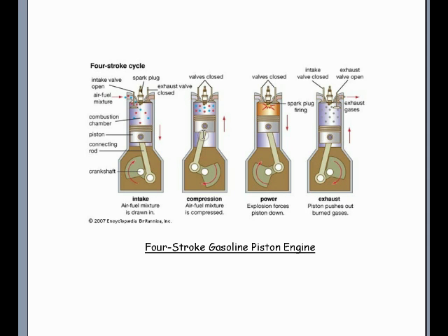Next comes the compression stroke, for which the air-fuel charge is compressed to before top dead center piston position, and at that point a spark ignites the fuel air charge, releasing combustion energy in the form of pressure exerted against piston area to create dynamic force to the power stroke. And then the next stroke is the exhaust stroke.